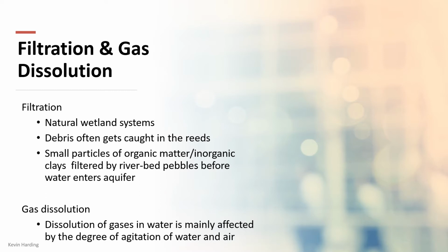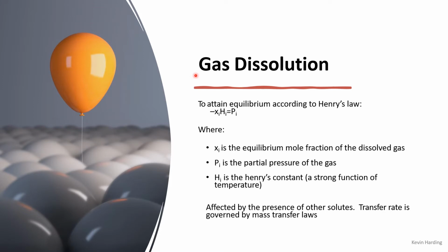Gas dissolution, the dissolution of gas in water, is mainly affected by the degree of agitation of water and air. So if you have a higher agitation, you have more dissolution of the gases out of water and back into the air. As I've already said here, I'm giving you the equation, but I'm not going to ask you a numbers question in this course, either in the test or the exams, but we would relate the gas dissolution to Henry's law. Henry's law you've probably dealt with in chemistry, and you're probably dealing with it in some of your other third-year courses. So now that you know where we can use it, some of the examples that you get in your other courses might be on environmental engineering.